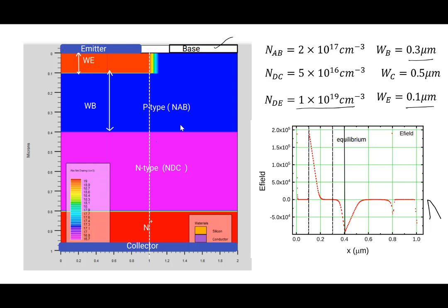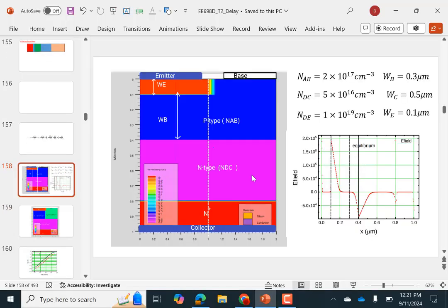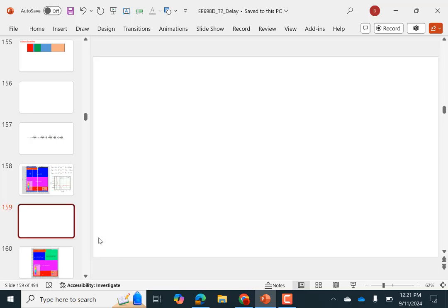So I'm going to do some calculations and also use Silvaco, which is a device simulator tool that solves Poisson's equation, the continuity equation and so on, and gives you current, voltage, capacitances, everything. So we'll use that for more accurate results, and our own simple analytical calculations to get an estimate and to understand. Okay? So this is the picture of electric field at equilibrium. Does it make sense? Electric field at equilibrium. 0 is starting here at the top, and as you go to 1 micron, you reach the other end. So does it make sense what you see? Maybe I should blow it up so that you can see it properly.